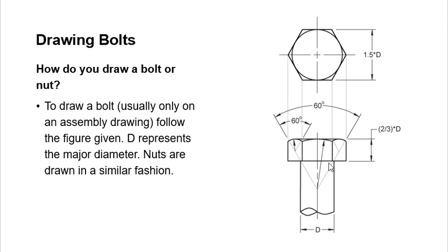From here all the way to here, that has got to hit the center line. So you can start with the angle and then go there, draw the head and draw the diameter of your bolt, and then extension, and then draw the top view. So here is your bolt head. From here to here is 2 over 3 times your diameter, which is this guy.